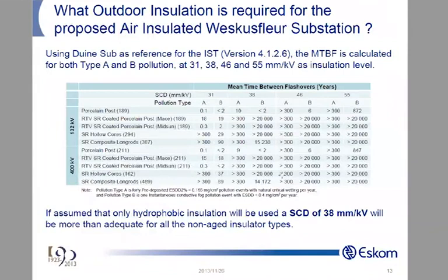And there's nothing wrong with the glass cap and pin disc. You guys have got some good experience with glass cap and pin disc, I'm certain. And also going for an RTV coated glass cap and pin disc is also a good idea. It's not a bad idea, okay? But the thing is this: it doesn't mean you have to go and re-insulate and get rid of all your composites, because you got corona rings on and you got them correctly installed, and you now need to just monitor and see whether they are okay or not.